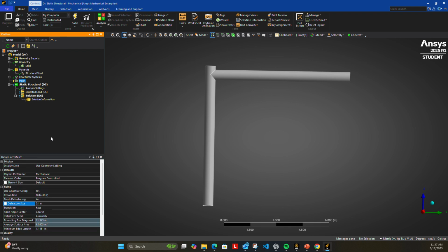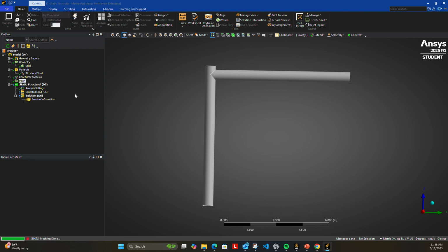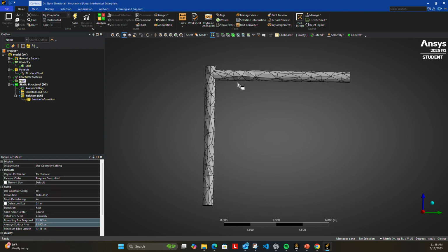And then it is going to create the mesh, take the data from the previous fluid mesh and interpolate that mesh's data to our current mesh. So your mesh doesn't have to be exactly the same, at least the surface mesh doesn't have to be exactly the same as the CFD mesh. Okay, then we can right click and update to create the mesh.